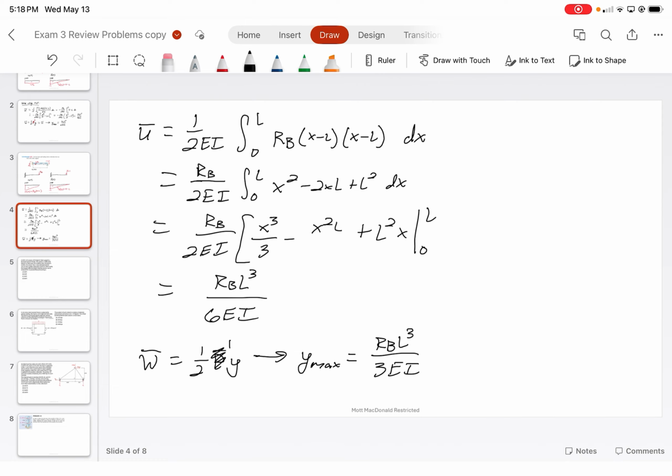Now, on an exam, again, I give you guys these nice little tables. You just wasted about 15 minutes if the deflections are on here. All right, which I will tell you they are, but it's good practice for this case. So I can tell you that for a point load, the deflection is PL cubed divided by 3EI.